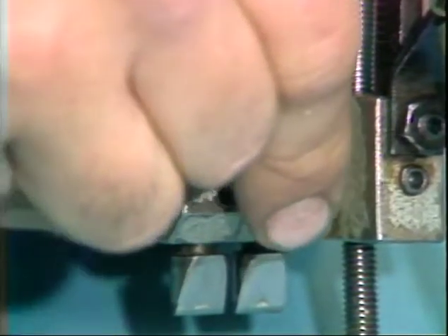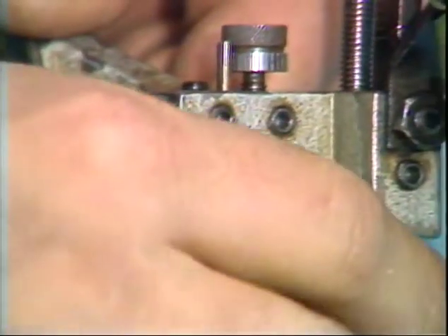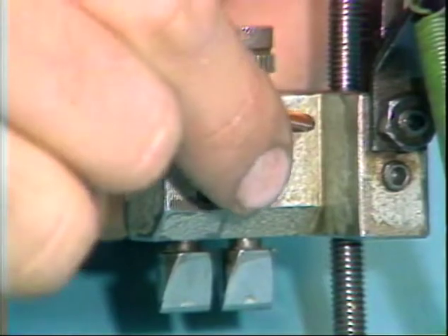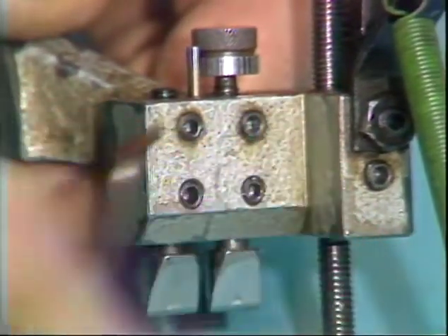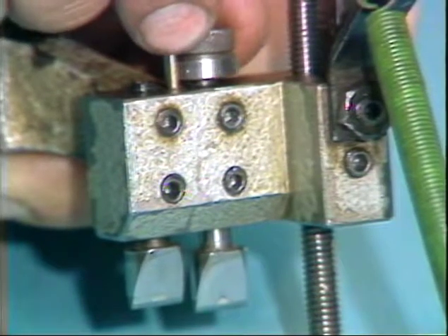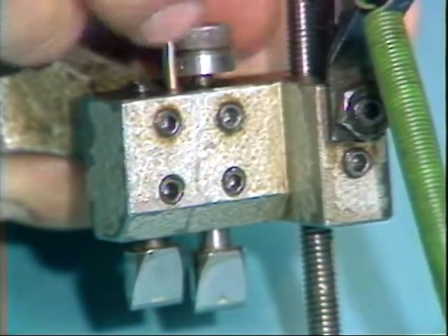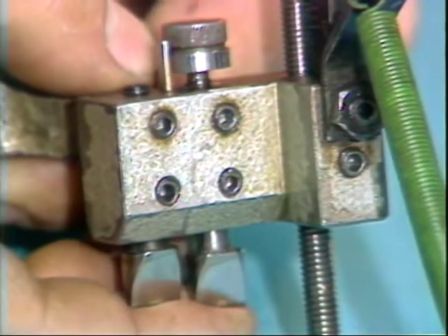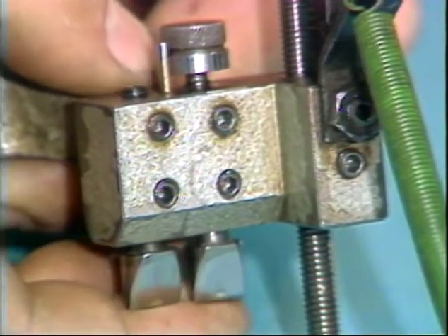Before mounting the attachment, the cam follower should be inspected and adjusted. Loosen the cam follower lock screw and the cam follower adjusting screw lock screw. Turning the adjusting screw clockwise will move the cam follower down. Turning the adjusting screw counterclockwise will back the adjusting screw off. You must apply pressure to the cam follower to move it back up.